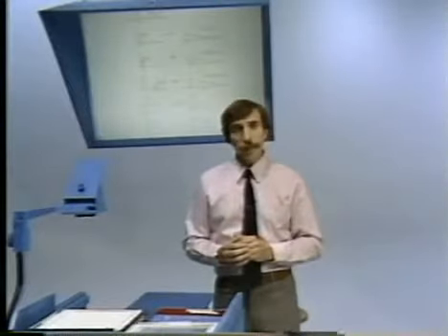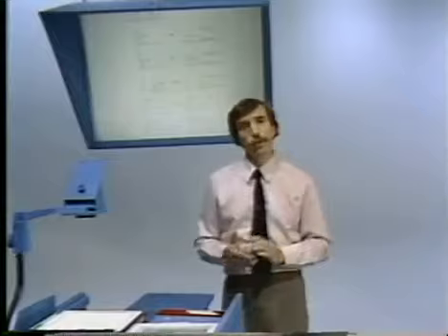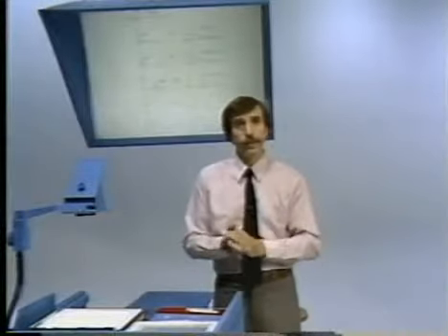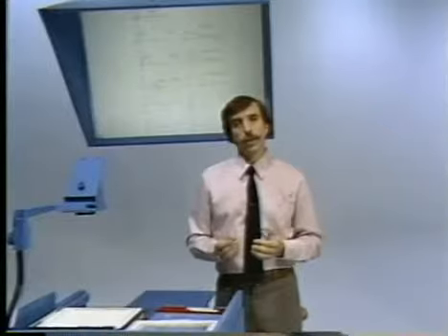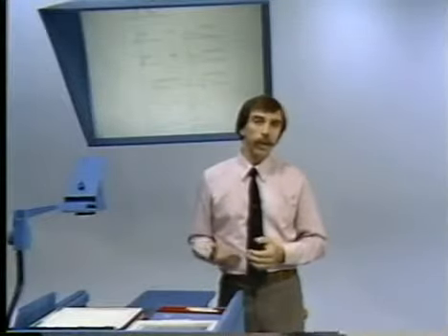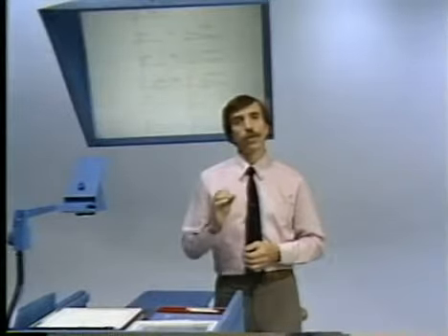Now, again, I stress that there is certainly a fair amount to examine carefully there, but it's important to also reflect on what we've done, which is really pretty significant. What we've managed to accomplish is to exploit the properties of linearity and time invariance so that the system can be represented in terms only of its response to an impulse at time 0.